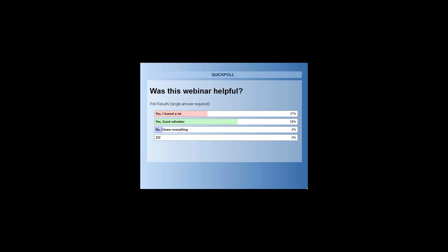And so speed control, keeping everyone close to the same speed, is going to be one of the best things you can do. From a geometry standpoint, I would say turn lanes help, because a good number of rear-end crashes are just folks that are slowing down to make a right turn on green, where the person behind wants to go through. So that's also helpful, and just access management. If you have your turn lanes, you have fewer driveways, you have fewer conflict points, things like that are very good. Yeah, absolutely.